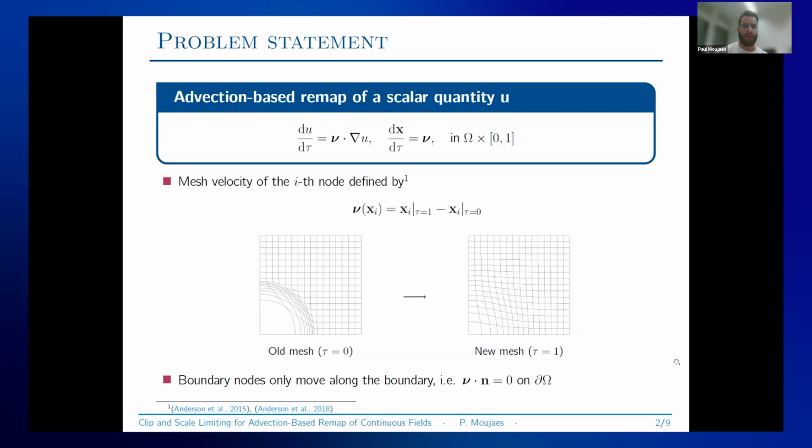as we can see here, for example, we have an old mesh which comes from the ALE solver. We want to remesh. We have quite skewed cells which might influence the time step restriction or similar things. We remesh to a new mesh, and overall we try to hold the velocity field, the shape in place, and remap this way.